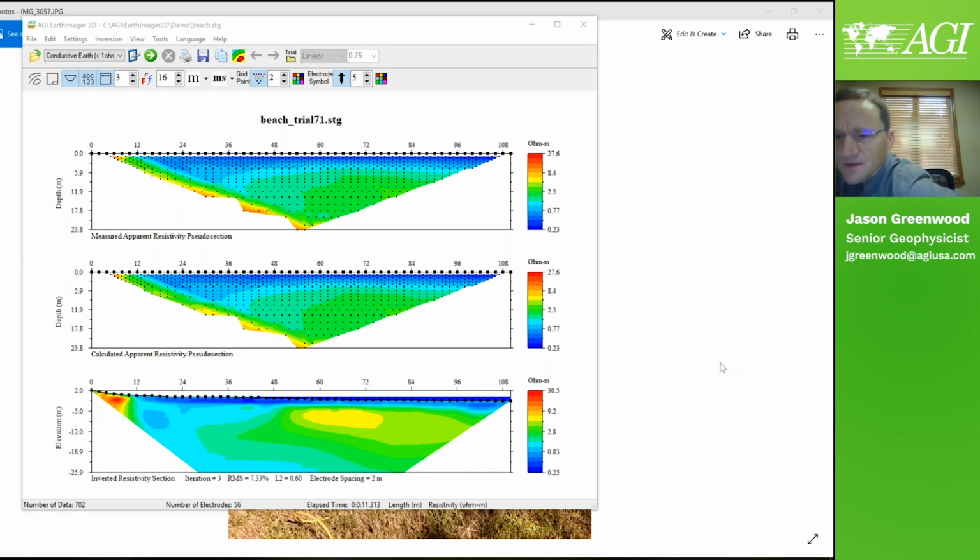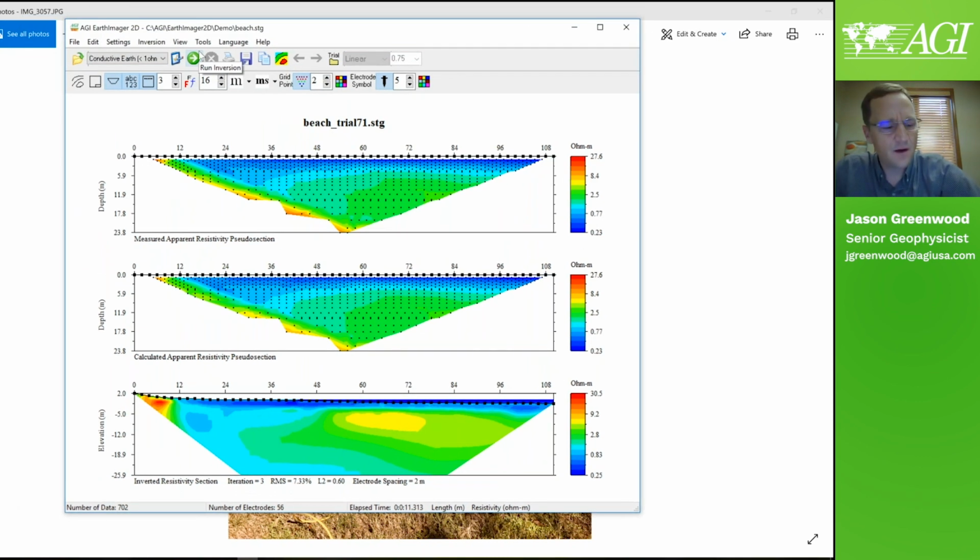Reducing contact resistance on electrodes when surfaces are dry and sandy soils. That's a good point. Contact resistance is your primary control on how much current you're injecting, and lowering that contact resistance is critical to quality data. If your contact resistance is below 1,800 ohms, you can use boost mode, and that's purely based on the impedance. Even if you had a powerful system, you couldn't transmit through some contact resistance. So lowering it is always best.